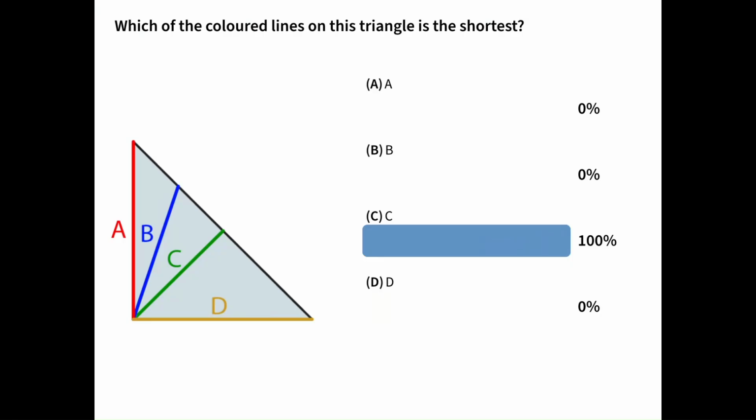So I don't think there's a whole lot of confusion here. Of course, when we're looking at a right angle triangle like this, the minimum distance is between the corner and the free face of the weld. This is going to be the face of the weld that's not fused to anything. It's just open. And the corner where the two fused faces intersect, of course, is going to be C, right?